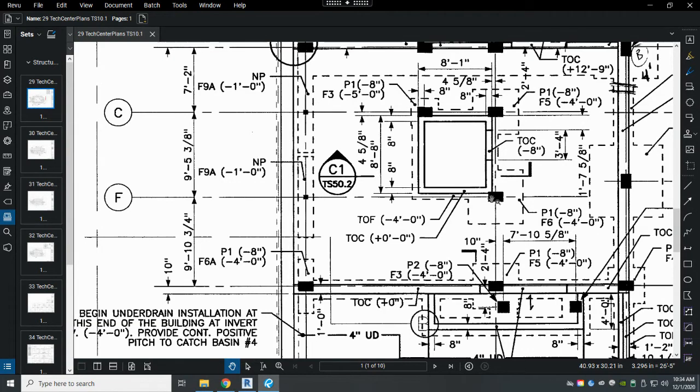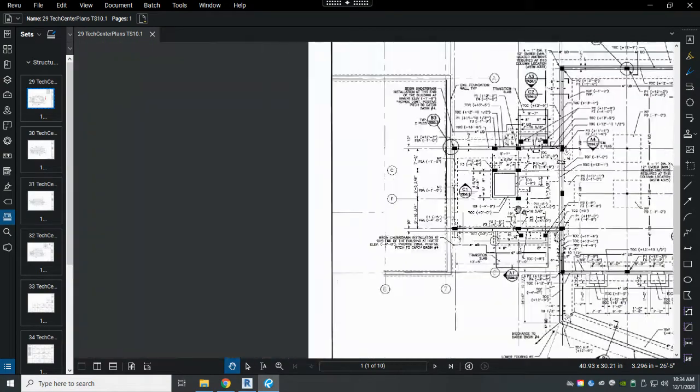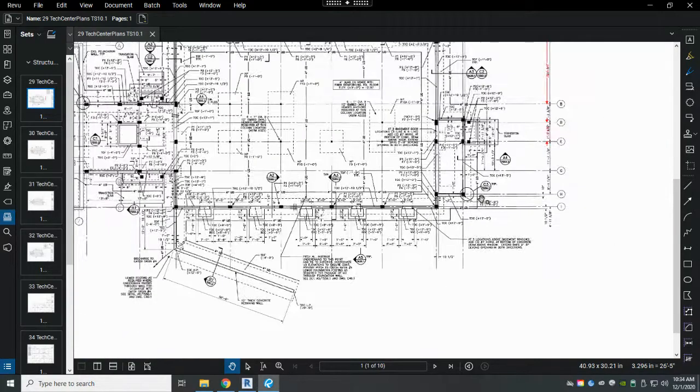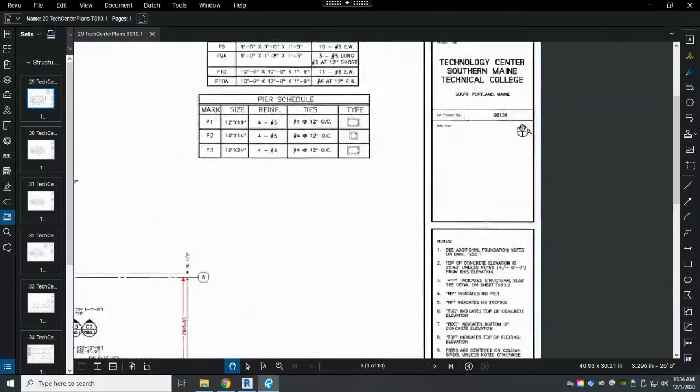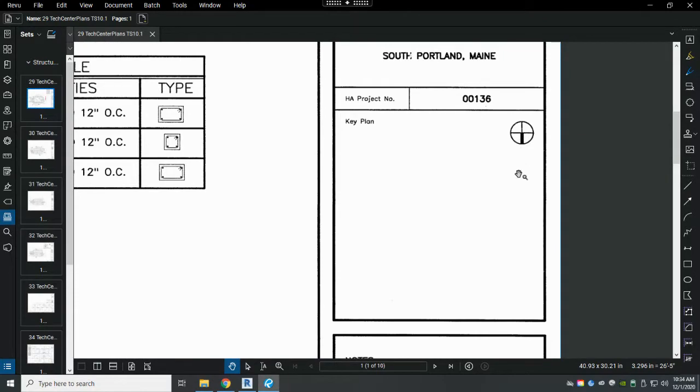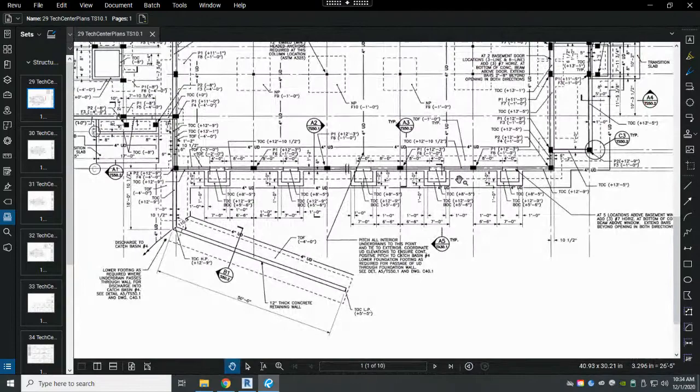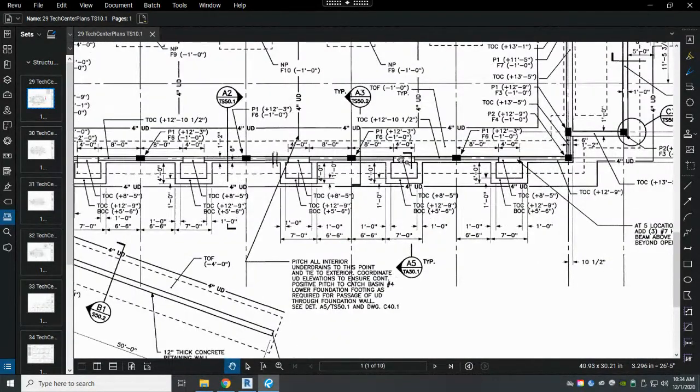What is the stem wall height of the window areaways on the north side of the building? So this is our north side of the building, remember. We found that out when we were looking at another set. Project North is down in this set, so that means this side of the building here is the north side. The window areaways are where these windows are located. There's an areaway that's been designed around it in order to use it as a retaining wall to keep the grade above these windows from caving in on the windows and actually letting light in.